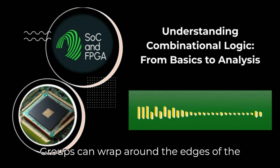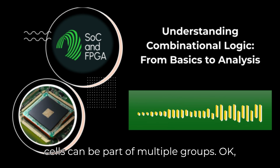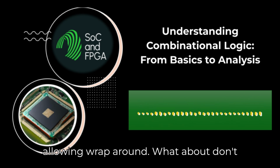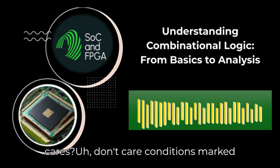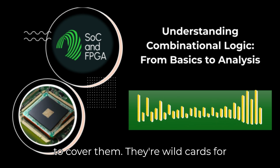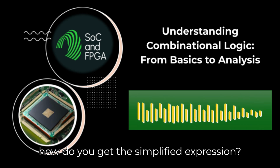Groups can wrap around the edges of the map, top to bottom and left to right, and cells can be part of multiple groups. Cover all the ones with the biggest possible power of 2 rectangles, allowing wraparound. What about don't cares? Don't care conditions, marked X, can be included in a group to make the group larger, but you don't have to cover them. They're wildcards for optimization.